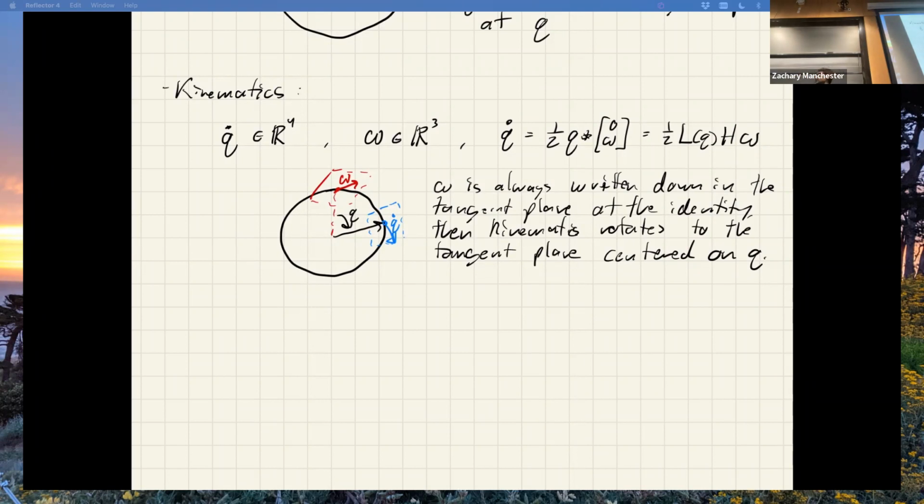No, it is globally singularity free, which is one of the big reasons to do this versus the Euler angle stuff. And the real geometry here, the whole Lie group idea, the underlying geometry of rotations really is this sphere thing. Going back to the globe, we're going to do this in a sec, but I'll just give you the whole story. Remember, we're talking about this unit sphere thing. That is geometrically what it looks like.